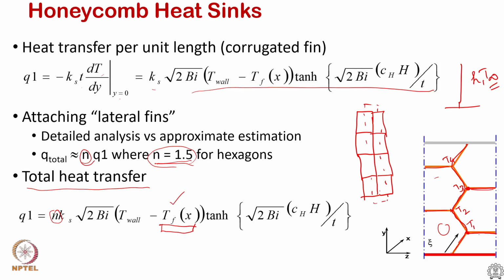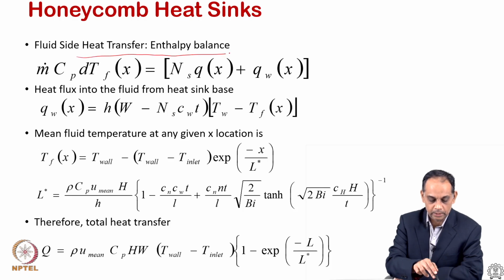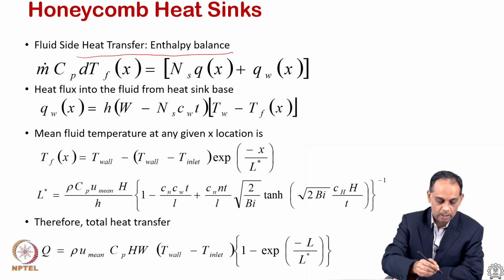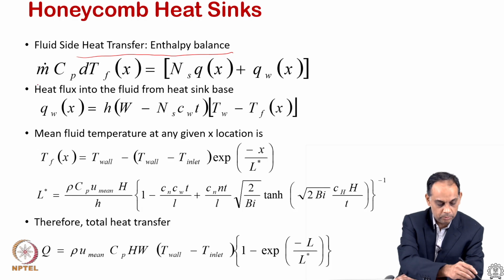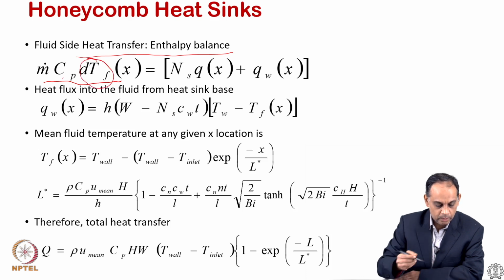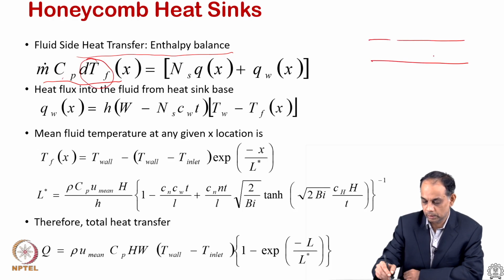So moving forward, we are going to take the fluid side energy balance, or the fluid side enthalpy balance, the fluid side heat transfer. If I take a single duct, a hexagonal duct for example, then I know my sensible heat rise is nothing but m dot, the mass flow rate, times specific heat times the temperature rise, and you can think of it as some kind of control volume. If I look at the side view of it, this delta